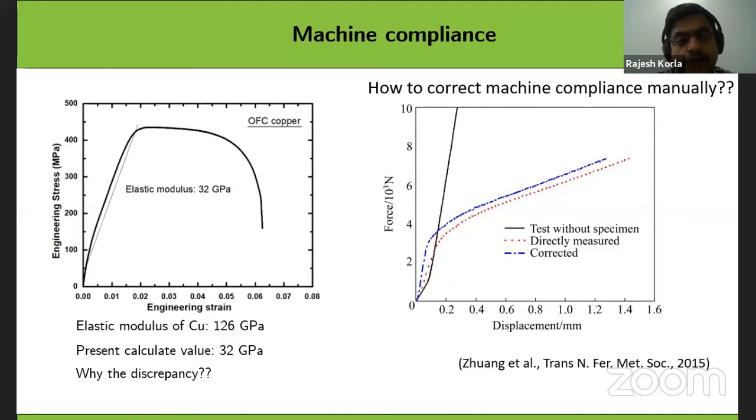One way is that you use, for example, compression experiments: take the sample out, and just compress with plate ends. With the plate ends, that means you generate a curve without the sample, which basically includes the relaxation from the machine at the different loads.